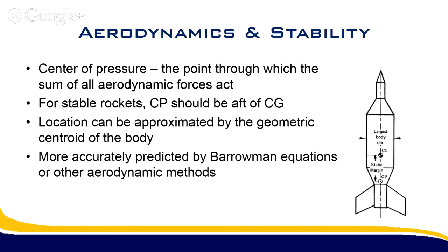Like we've told you since the beginning of whenever, it may be for you, that center of pressure should always be well behind the center of gravity, which is where, if all the mass forces were centered in one place, it'd be the CG. We say it should be one body diameter behind that CG.